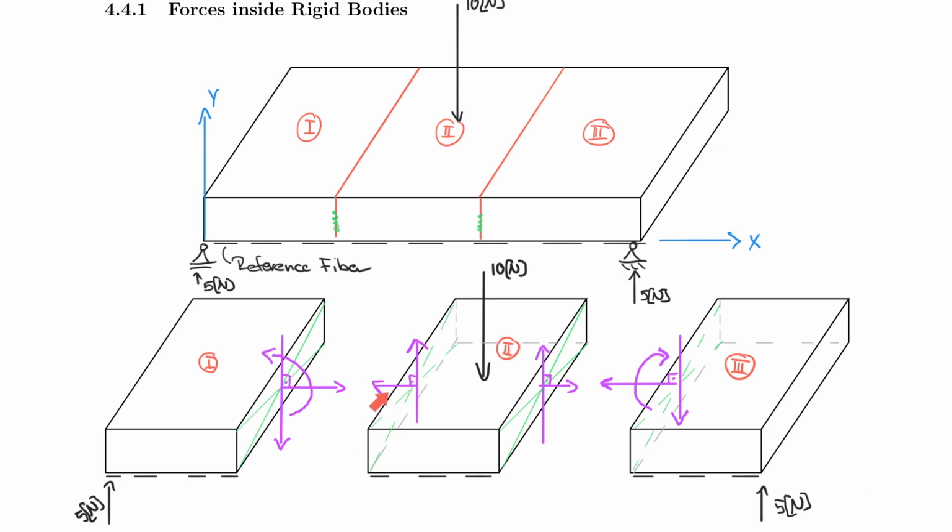And so these cuts here, the space in between, is actually in equilibrium if you want to think about it this way, because this force is pushing on the cut and this force is pushing in the opposite direction on the cut. And so what I'm trying to tell you is that it doesn't matter if you only look at this system here, only number 1, or if you look at 2 and 3 together, the normal force here comes out to be the same as it would come out here on this side.